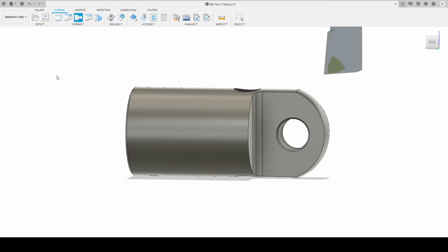It won't change tools, and if it does, you won't get the retraction, and it could index the turret right here when the tool hasn't relieved itself from the part, if that sort of makes sense. So we'll get into that later, but for now you should be alright, because we're going to create our tool libraries for you, so they should all have unique numbers.